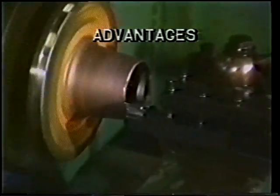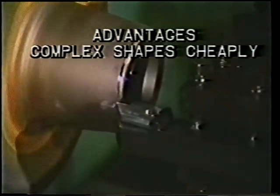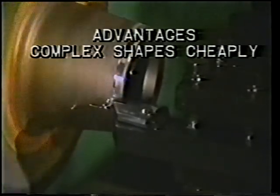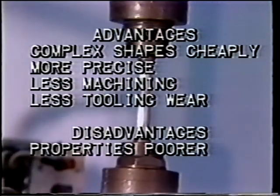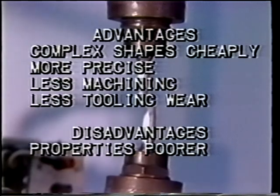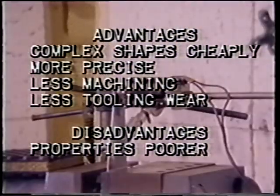There are many advantages to casting over other processes in producing parts. Oftentimes, complex shapes can be cast much more cheaply and easily than machining. It is also more precise and requires less subsequent machining than forging. There is also less wear on tooling than in forging. On the other hand, properties are generally poorer with castings than with forgings. Though high temperature stress rupture qualities are better, important room temperature fatigue properties are not as good.